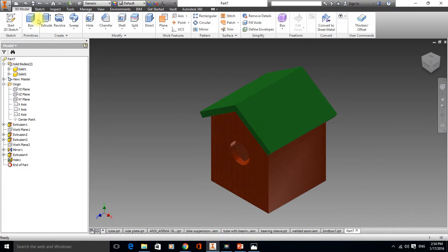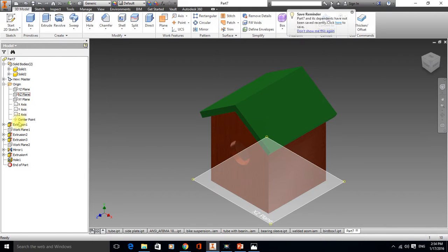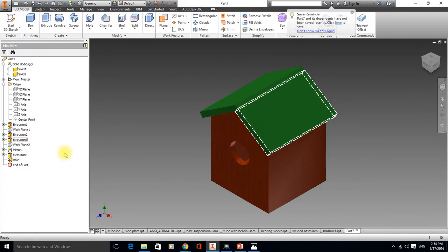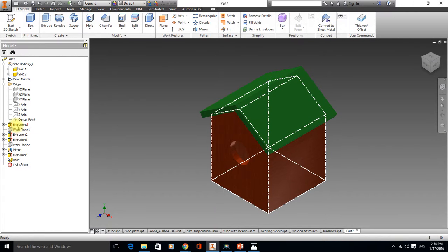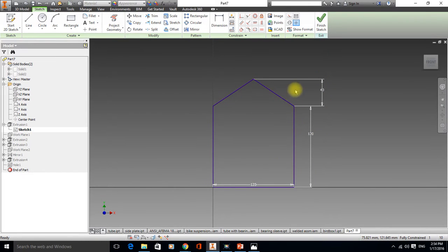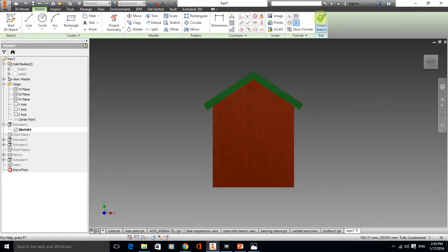Okay. And that was all using 2D sketches, constraints, snaps. Down the left hand side you can see everything that we did. If you want to adjust anything, all you've got to do, plus sign, you can click your sketch, you can click the icon that comes up here, and what that will allow you to do is actually edit your sketch, so you can make adjustments to it. If you're not happy, go back and actually move things around.